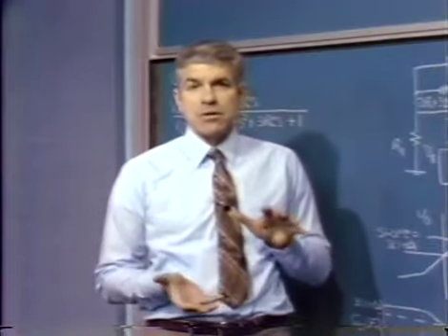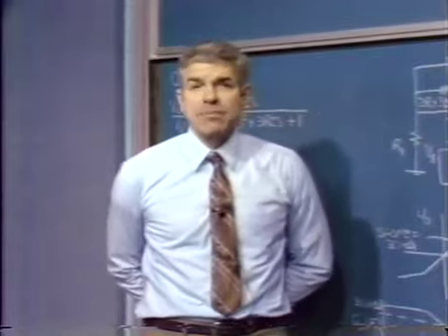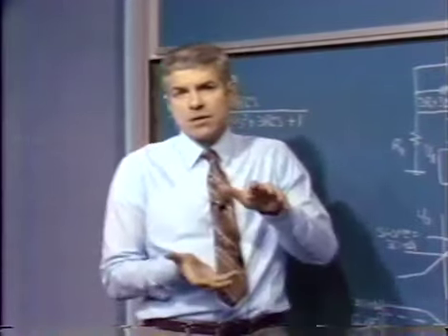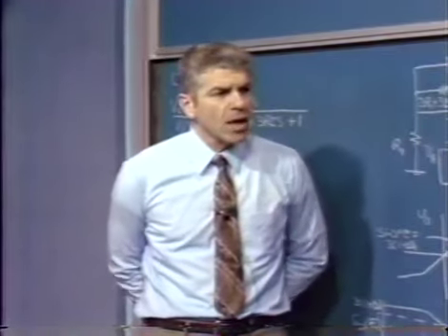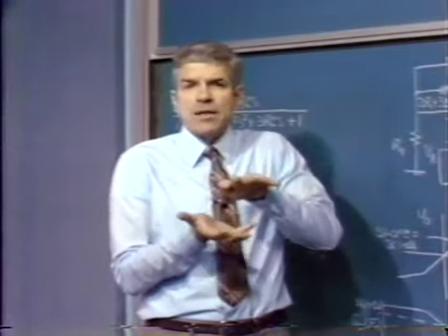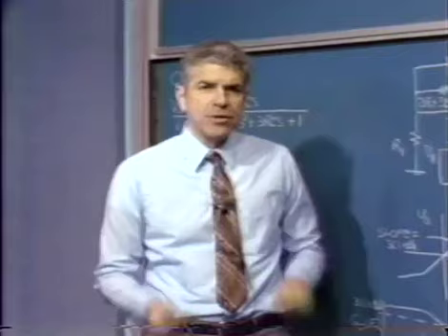As the signal got bigger or smaller, the resistance of the lamp changed because of heating in the lamp. That occurred with a very long time constant, at least compared to the period of oscillation. And the resistance of the lamp changing would automatically act to stabilize the amplitude of the oscillation. It's kind of an interesting passive, if you will, feedback system.